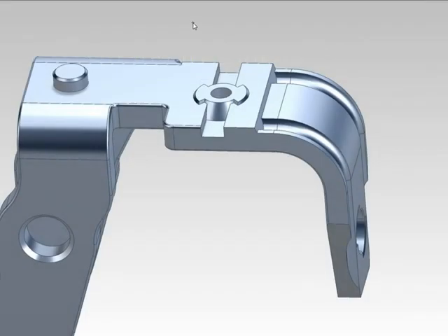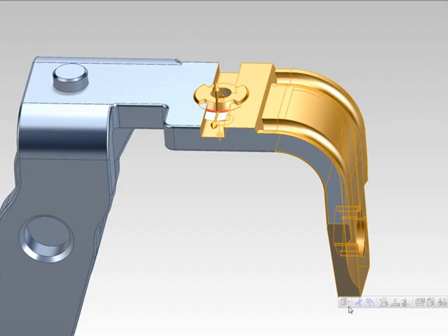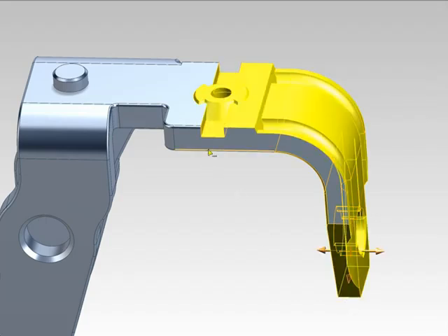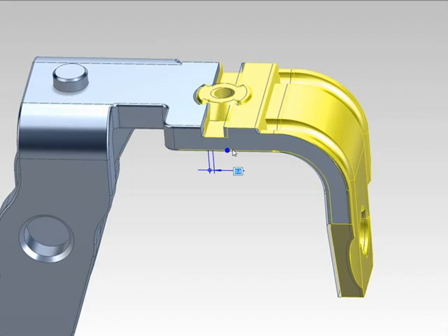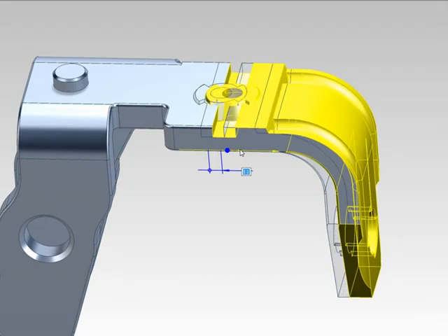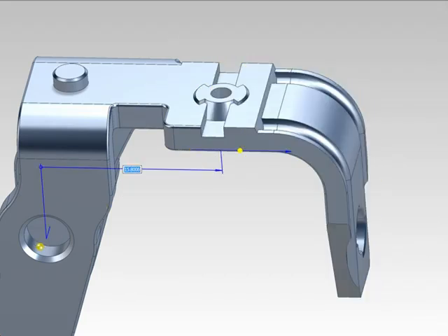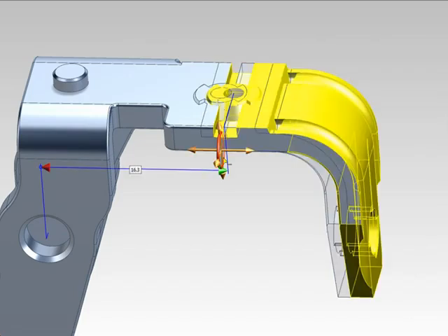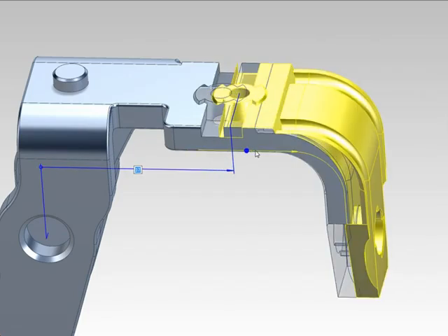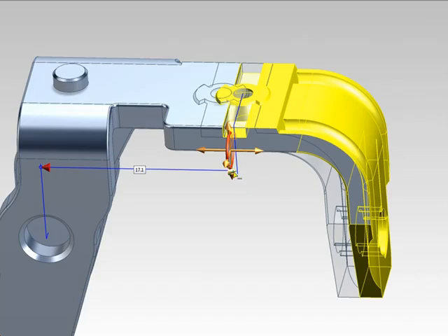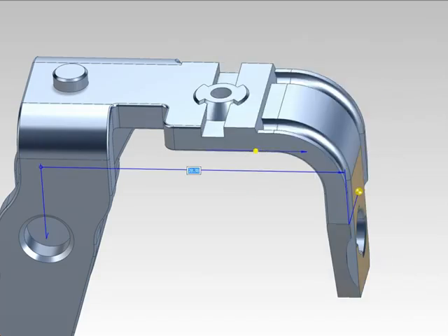Another major improvement are the on-the-fly dimensions that include linear and angular measurements. Notice how the change is done in real time without the need for preview. I just select the geometry with box select and drag with the 3D Copilot. I can redefine the dimension references by moving the fix and move points, making it much easier to use relative measurements without using intermediate steps to measure the distances and use the results for the change. I can enter values directly.